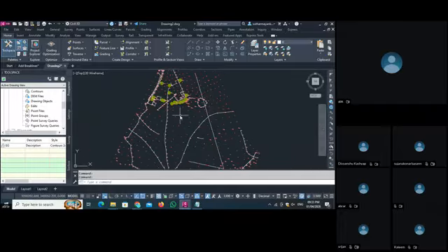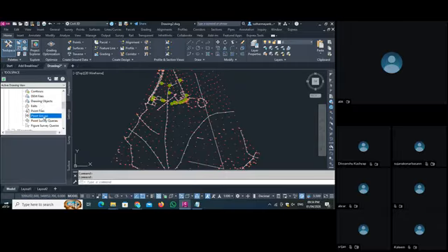What I do, I want to tell Civil 3D that I want to put all these points in the easy folder that we created. So when we import all these points into this easy, then Civil 3D understands that yes, in the surface I have easy, and I have to make this easy with the help of all these points. To import all the points in this, we go here to the point group,